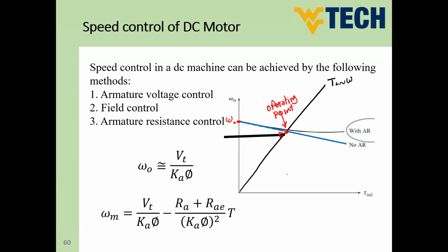So if I run this motor at this characteristic with this load torque, the machine will start working until reaching that point. This point is going to be the steady state operating point. This is the value of load torque, and this is the value of load speed. So this is going to be our omega m in this loading condition.